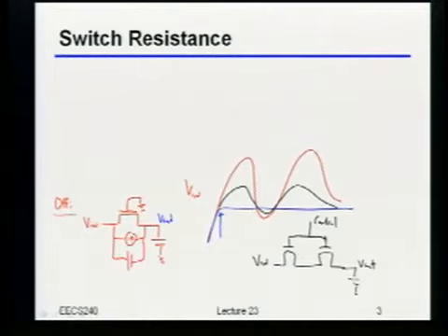Okay, now, so far, I haven't done a whole lot other than make my switch twice as long as it used to be from a channel length standpoint, right? But I claim if I modify this thing ever so slightly, there's something very nice I can do from the isolation standpoint. So what's nice about having two physically separate switches? You could put a low impedance thing in the middle. There we go, exactly, right? I can actually hard ground that middle point, right? I can force it to a known voltage.